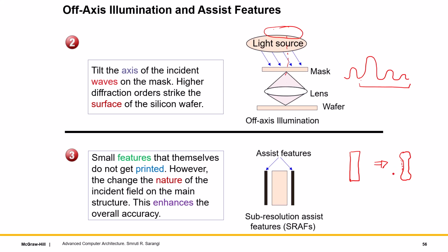So of course, you can say that I can use optical proximity correction, or OPC, and try to fabricate something like this. But the other approach is to have these tiny features over here, which literally are tiny, in the sense that nothing will get printed here, right? The main reason being that they're very, very narrow.